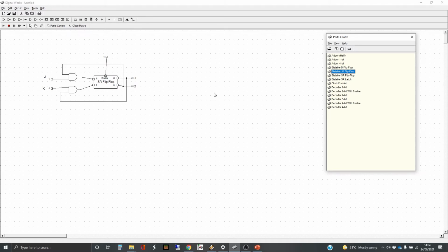This is one version where we've got the S linked up to an AND gate. We've got the R linked up to an AND gate. We've got our J and K. The letters J and K, I have no idea if they actually mean anything. I think they're just letters that happen not to be used elsewhere, so somebody decided to use them for this particular type of circuit. And we've got a crossover feedback, which is similar in some ways to the very basics of the SR latch, which is somewhere below the hood here.